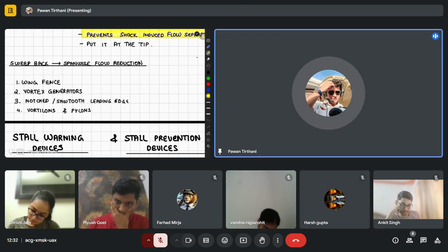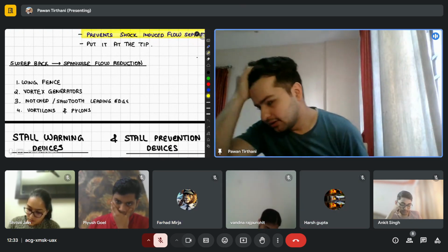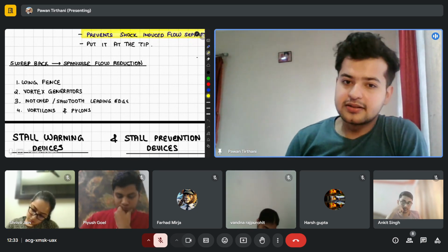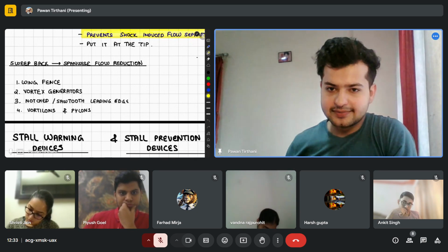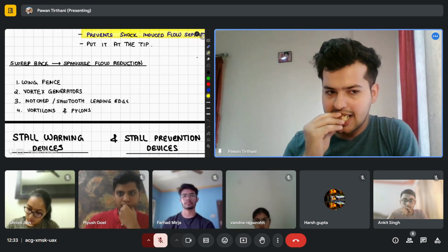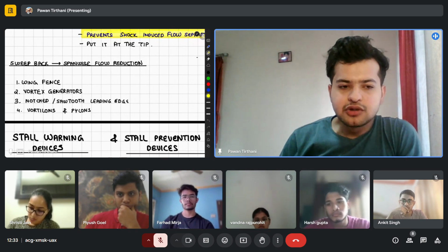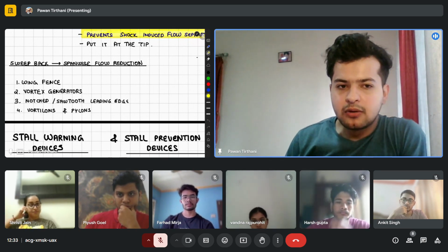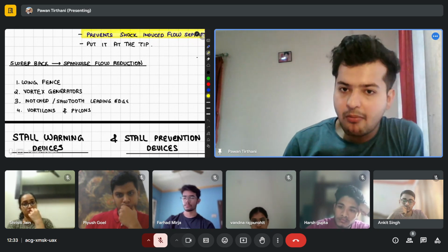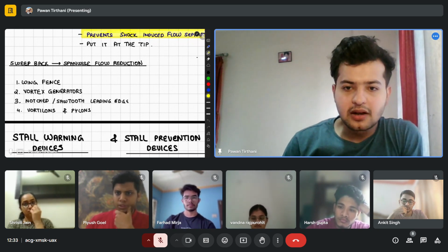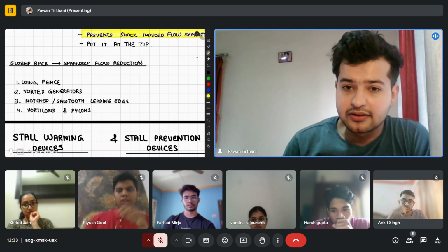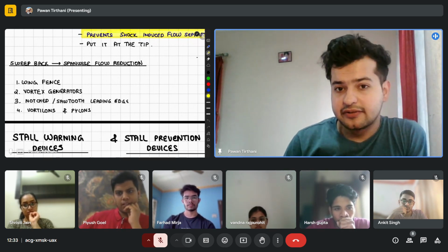Okay, let's शुरू करते हैं ना. So now let us try to fix the span-wise flows. Maybe here you'll get your answer, Piyush. What you also saw was a sweep back wing, right? So in sweep back wings, what we want to do is reduce the span-wise flow from the leading edge itself, right? And how do we do that? We use wing fences. What is a wing fence?